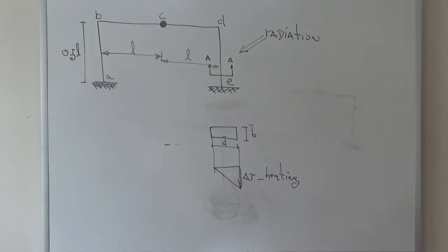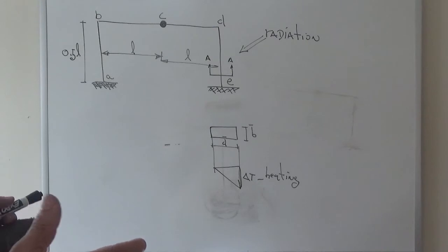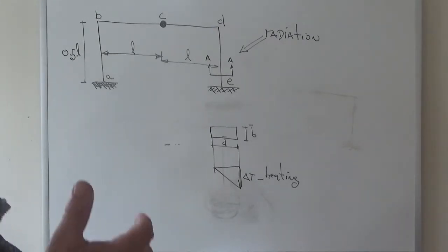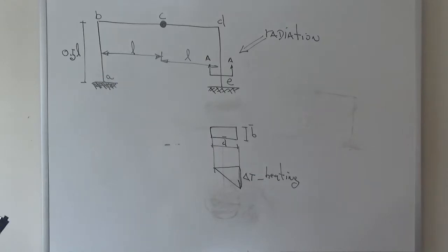Because in structures that are statically determinate, the changes in temperature do not induce any moments or shears because the structure is able to accommodate the changes in shape that are demanded by the temperatures without the need for moments and shears appearing.